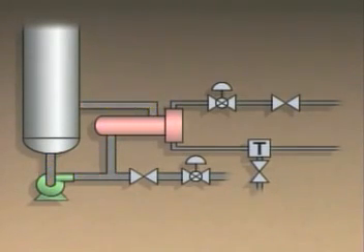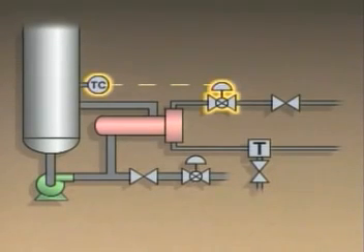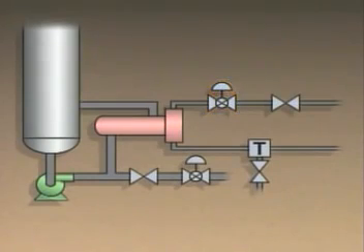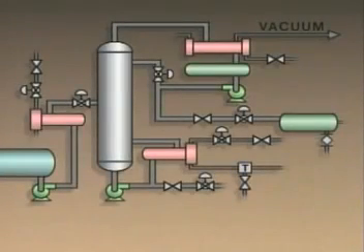To enable that liquid to cool before it's drained from the system, a temperature controller is manually set to close a control valve in the reboiler steam line. An isolation valve in the steam line is closed as well to ensure that no steam reaches the reboiler. The reboiler's circulating pump is left on for now to help cool the liquid and equipment. At this point, there's no feed going into the column, and the overhead and bottoms mixtures are being recirculated.